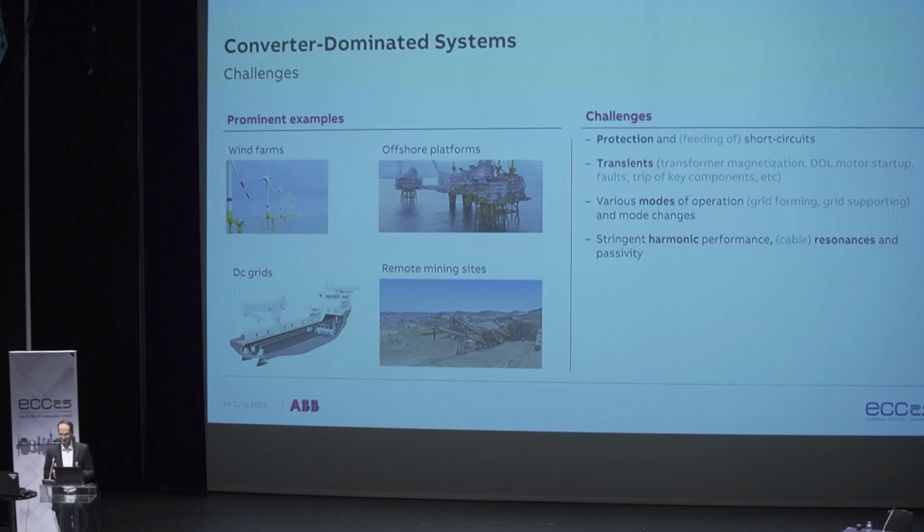And maybe what is the hardest here is protection. So whenever you have a fault, you need to make sure that you identify the fault and open the appropriate circuit breaker. And power converters are not suitable for high overload. They're not made for that. So you can overload them only for a few, maybe milliseconds, but maybe not long enough. So here they have a shortcoming. So we should probably think about better ways to do protection.